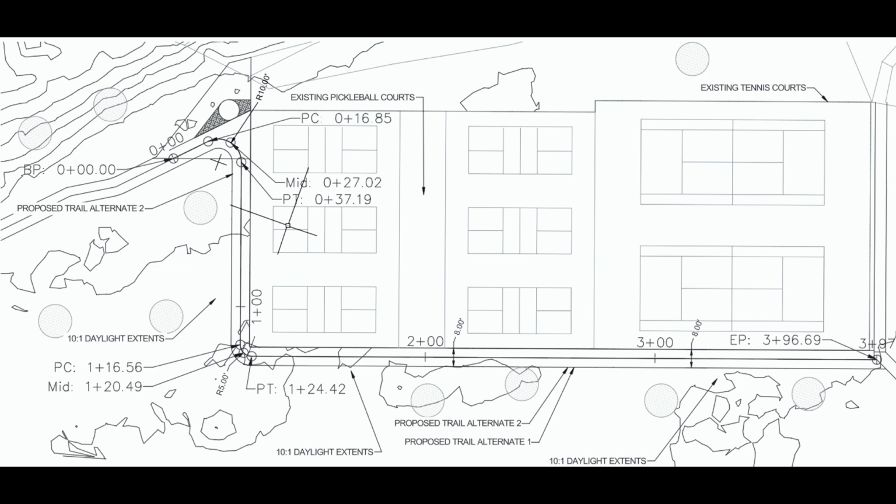After that, both Trail Alignment 1 and 2 have the same design until connecting to the existing sidewalk along South Main Street. For both of our designs, we chose crusher fines as the trail material. This keeps construction costs low and maintains the park's natural look while providing a stable, durable, and accessible surface. Either option will address the needs of the client and community of Buena Vista.